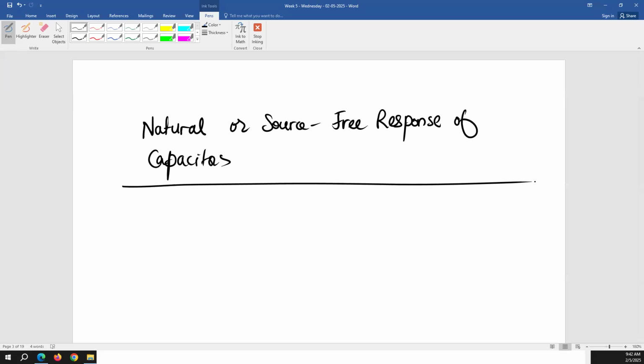So the idea here is that you have a capacitor in a circuit, and you are exciting that circuit with a DC source. You're not using a function generator or an AC source or anything, you're just using your DC power supply. So when you excite a circuit that has a capacitor and resistors with a DC power supply, then the capacitor starts charging, right? And as we discussed on Monday, the capacitor is going to charge up to the maximum amount of charge that can accumulate on its plates. Once that happens, the capacitor cannot accumulate more charges.